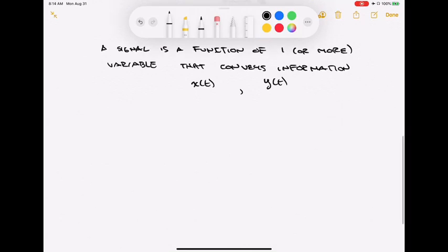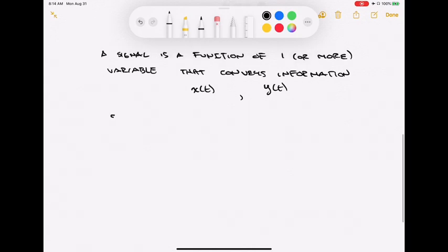I'm going to just follow book order in the following presentations. It's a little hard at this point because we're starting from scratch, and it's a little awkward because you don't really have the introduction of everything. So you've got to start somewhere. What I'm going to start with is one way of classifying signals. We can classify signals based on their size. So let's look at signal classification, and here we're going to talk about the size of a signal, and we're going to measure that size through a concept of either energy or power.